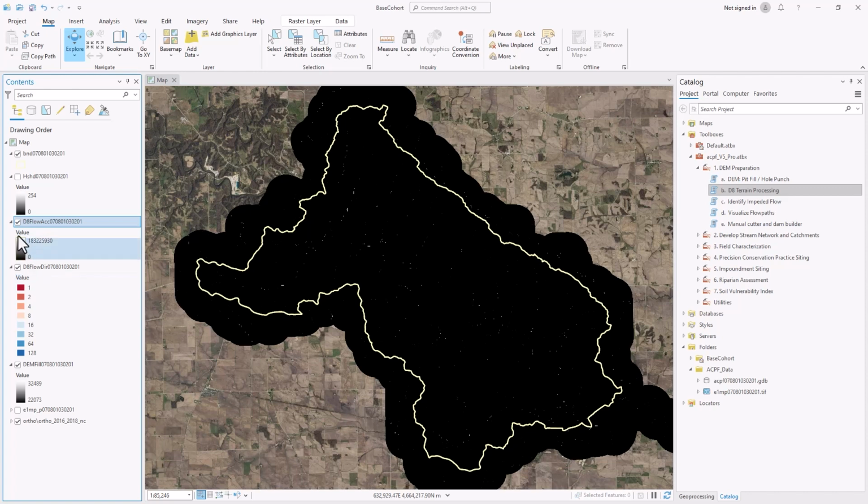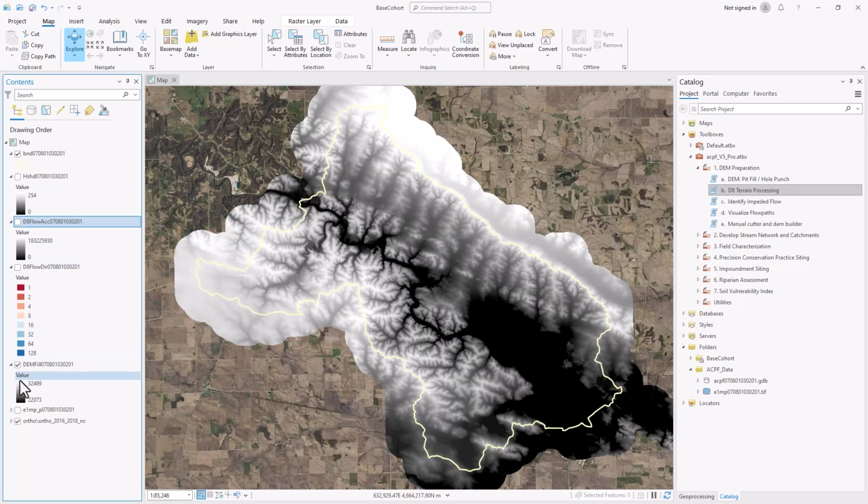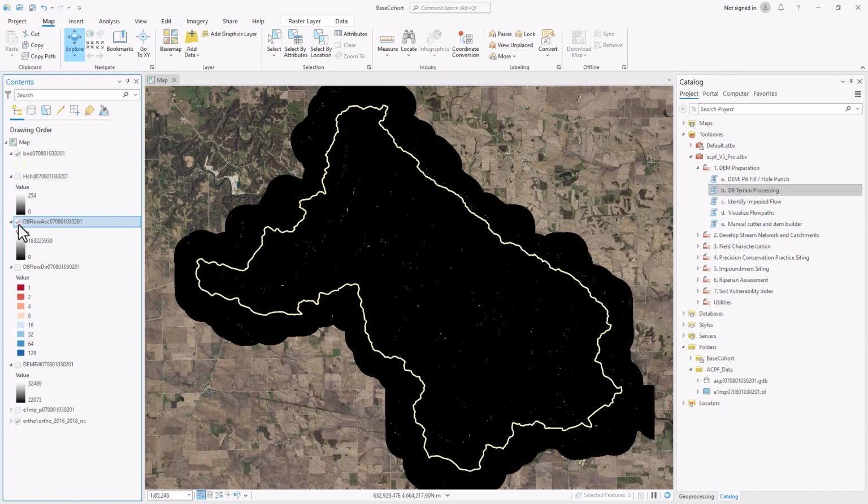And third, we see the flow direction raster titled D8 Flow DIR, which has had the symbology changed and looks absolutely crazy. And then we have the filled DEM titled DEM Fill, which at the moment looks just like our original DEM, though the sinks have been filled. As you can see, we are unchecking all, and we will turn the D8 Flow ACC back on with all within our table of contents. Right now, we're not seeing much with the flow accumulation, but with some visualization, we'll be able to see a whole lot more.